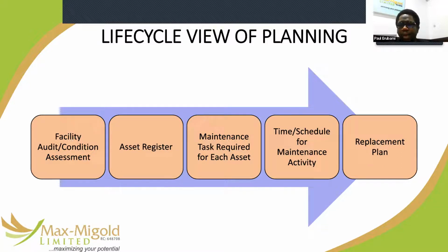In fact, that is a very bad practice, because the other assets that are supposed to work with run-to-failure or predictive strategy, you have ignored them. You have not adopted those strategies. You are not maintaining them. You've not even created a plan for how you're going to manage and maintain them. And in many cases, you don't have a budget to respond even for the run-to-failure assets. You go cap in hand to management every time you have an issue, and you look very irresponsible over time. And that is because you created a maintenance plan that did not encompass all of your asset register.